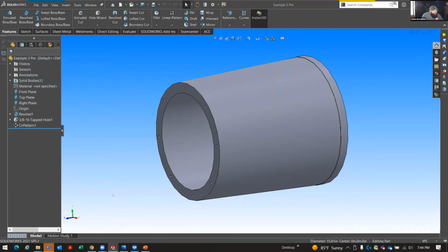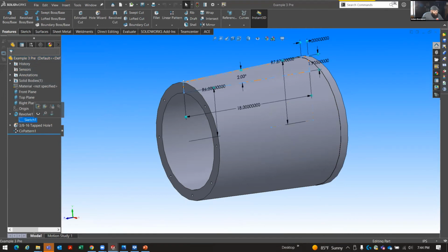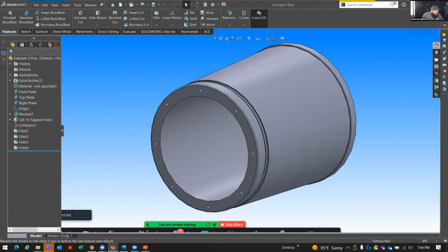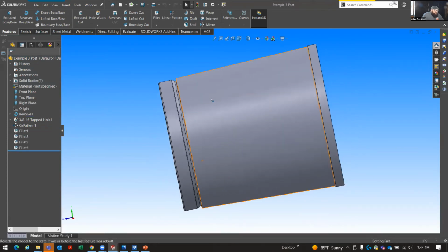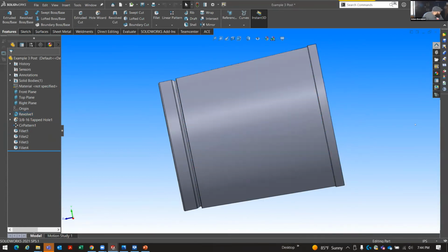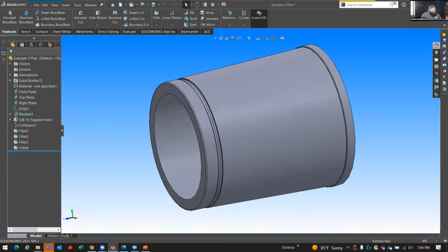So we actually jumped into SolidWorks in our CAD machine here and decided to scoop out some material, and only had a small section of it. We actually ended up knocking off like 3 inches off the actual taper so that you could slide this thing on a little bit more efficiently and save some cost on it.